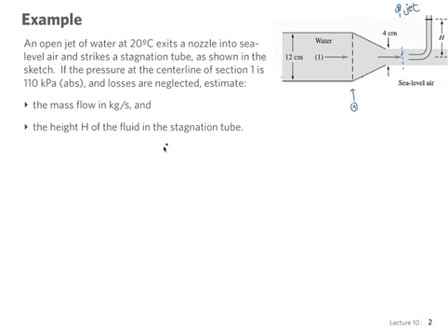Okay. So let's write down Bernoulli equation between that station 1 and the jet itself. So P1 plus 1/2 rho V1 squared. I immediately am going to neglect differences in elevation and write, this is a free jet, so it's an open jet, therefore I'm just going to write P0, indicating that is atmospheric pressure there, and 1/2 rho V jet squared.